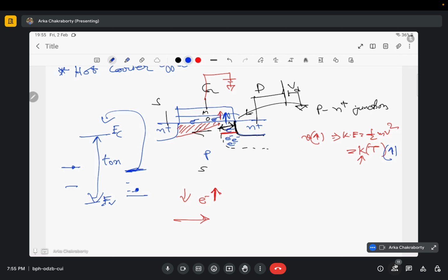If you have studied device level physics, you know that in a MOSFET, when there are charges present, the threshold voltage of the device shifts depending on the charge. So these electrons can shift the threshold voltage to a new value, Vt plus delta Vt. The current that you get for a particular VGS and VDS will change, and your device will start giving degraded performance. This is called the hot carrier effect.